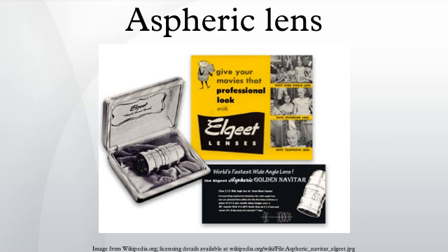Several finishing methods can be used to improve the precision and surface quality of the polished surface. These include ion beam finishing, abrasive water jets, and magnetorheological finishing, in which a magnetically guided fluid jet is used to remove material from the surface. Another method for producing aspheric lenses is by depositing optical resin onto a spherical lens to form a composite lens of a spherical shape. Plasma ablation has also been proposed.